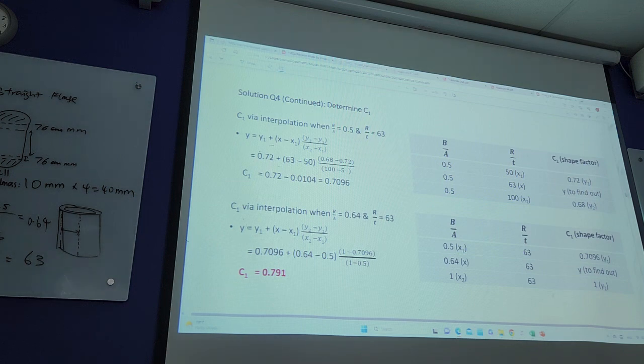Anyone have any doubt about this? Because without finding out the C1, C2, you cannot do this longitudinal stress calculation. So I'm taking effort just to explain to you the interpolation. You must know how to find the final value of C1, because the table given to us doesn't have the value of what we want, alright? Because we calculated from our pad size, right?